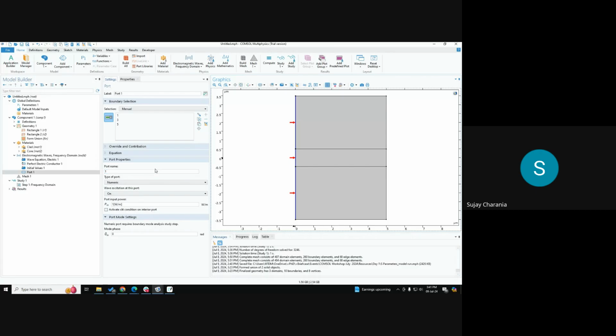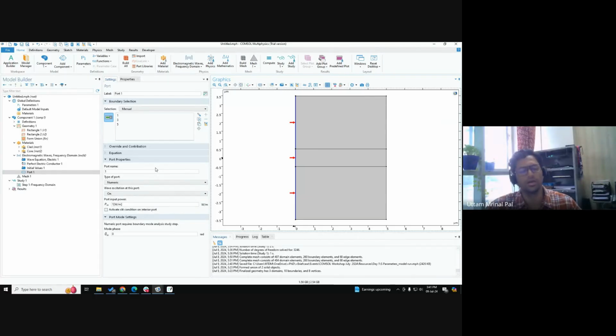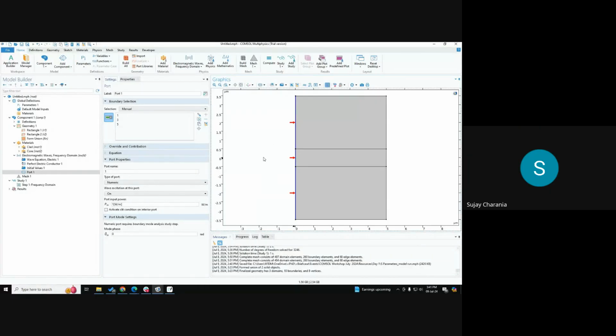And the second one, have you seen this misalignment in COMSOL? Can we try aligning, changing the position by some micrometer here and some micrometer there and see how it behaves? For example, if you only want to excite the fundamental mode and you find the best position, then you misplace the source and you see that not only the fundamental mode gets excited but also some other modes are excited, and those lead to more losses and so on and so forth. That's a very interesting study actually.